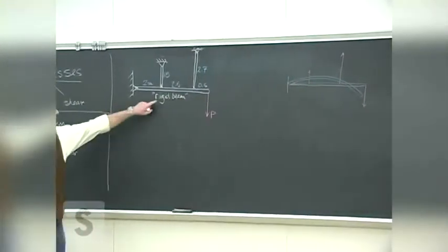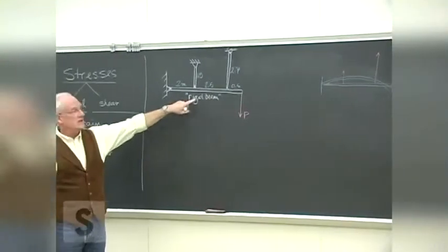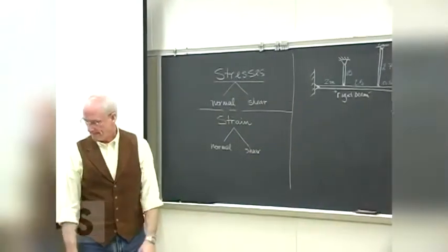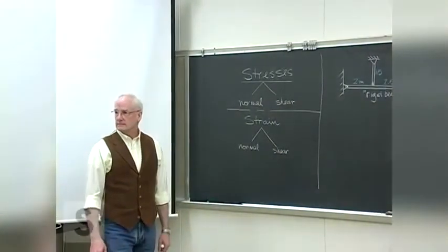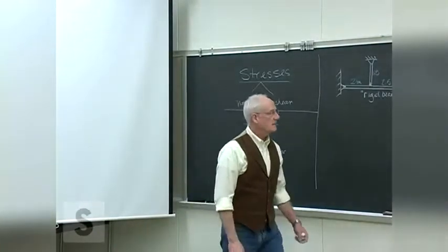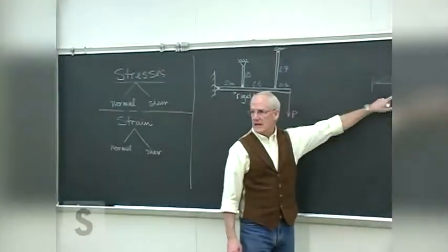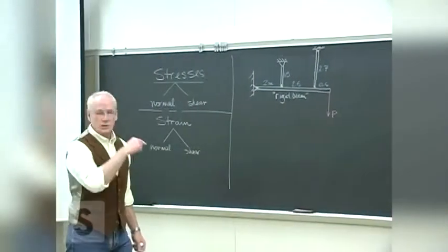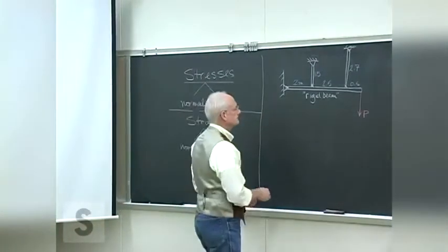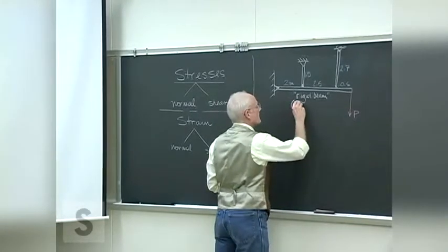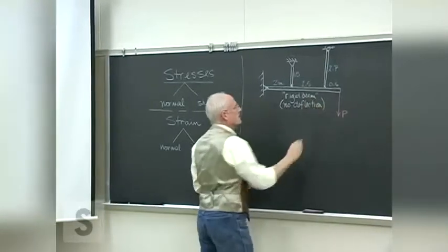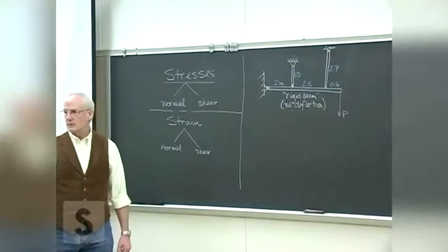We're going to assume, with the rigid beam assumption, that there is no deflection like that in this beam. It's not accurate, of course, because the beam will deflect like that, but that's something we hit much nearer the end of the class. In the last month of the semester, we'll look at the deflection sideways of beams to transverse loads like this. So, rigid beam, no deflection under the load applied.